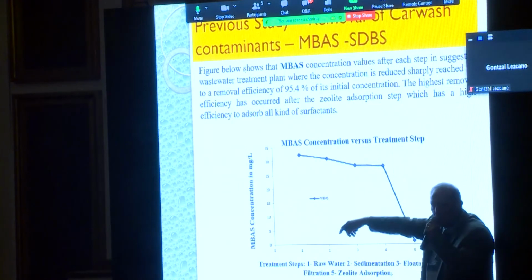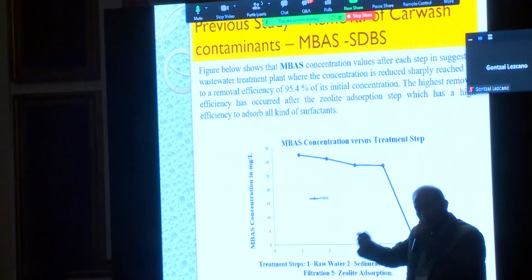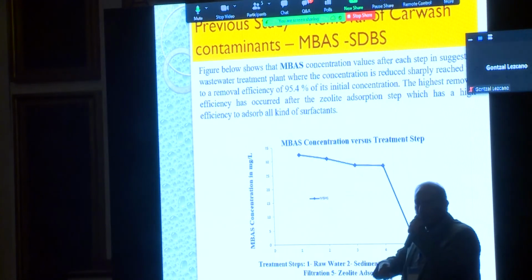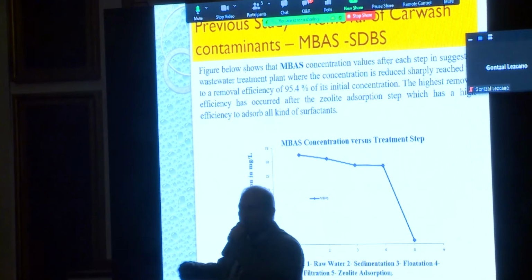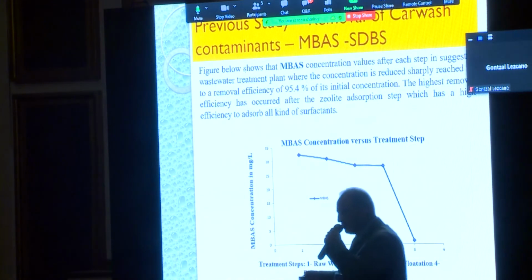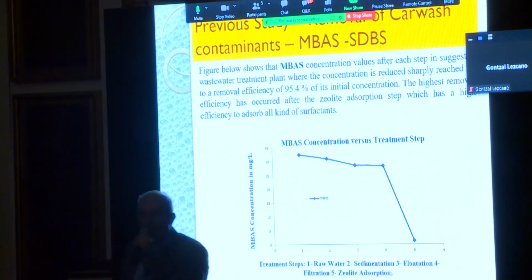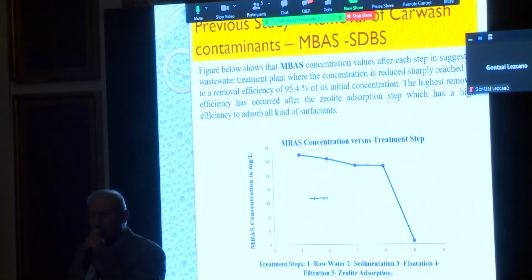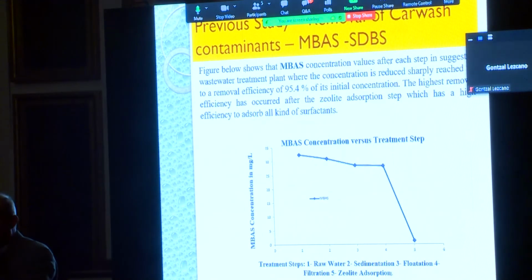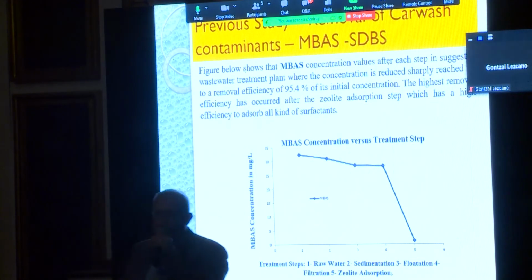When we use the natural zeolite as an adsorbent, we prepare it by crushing, washing, and soaking in diluted nitric acid to get rid of volatile organic compounds, and any impurities can be oxidized by this system. And finally, we prepared a set of experiments with different adsorbent doses. Our adsorbent doses were 0.1 gram of the adsorbent, 0.5, and finally 1 gram. A lot of experiments were done to determine the removal efficiency and the contaminant uptake.